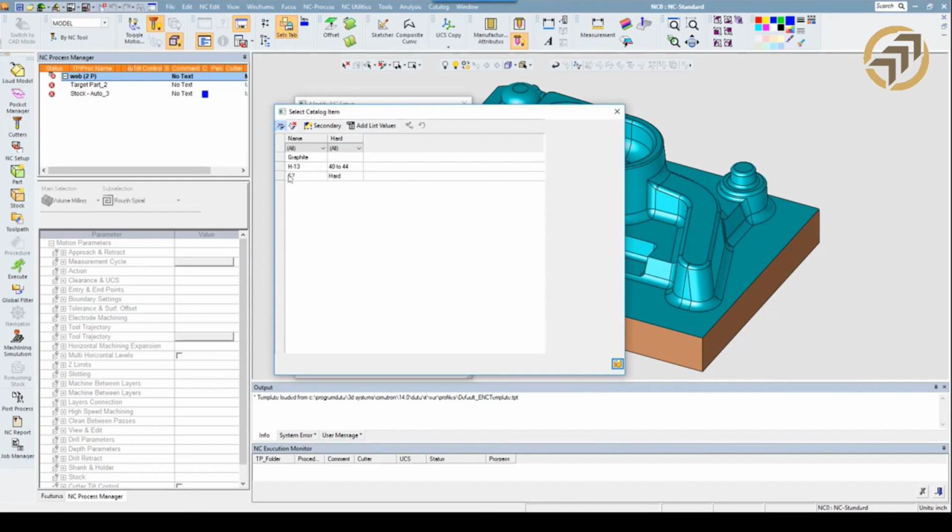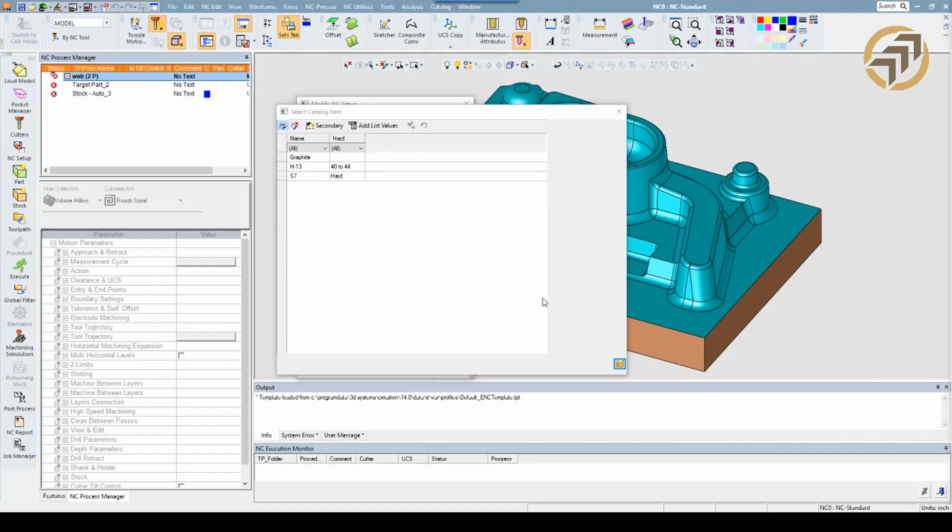Here you can right click and you're able to insert or delete. I'm just going to add one, P20, and if you want to, you can give it a hardness 38 or just write something in if you have stuff before or after heat treat. Hit the green check, and now that's added to your material list. If you want to delete it, just right click, delete the row, and apply it. Okay, I'm just going to close out of this window.